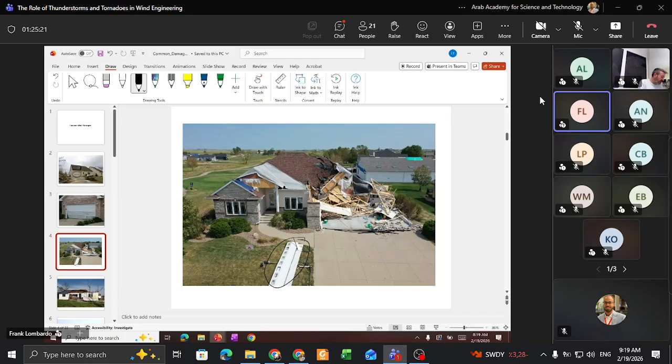Pretty much everywhere else in this area, the damage was minor. You can see some minor roof damage here. In the U.S., typically after these wind events, they'll cover the damage with plastic or vinyl tarps. They'll put them over the top of the building to protect it from water ingress and things like that.